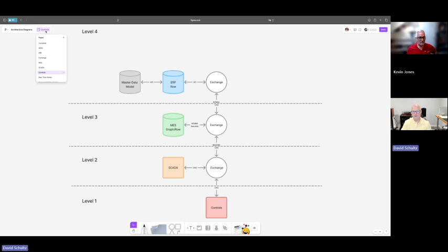So now that we have taken all of our data, we've modeled, and we have really good architecture and really good design and governance from our level 4 down to our level 1, now we need to start getting that information back so that people can start consuming it. Where you're typically going to find that first, at level 2 SCADA, that data acquisition piece, is some sort of time series database, or a process historian as it's generally known.